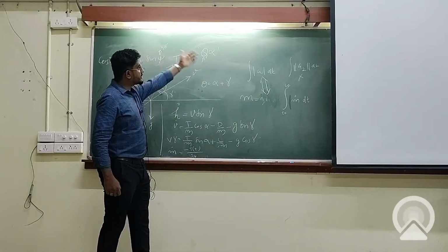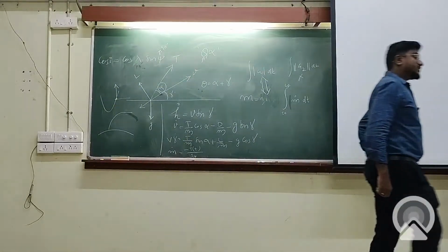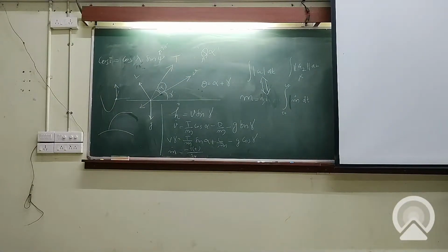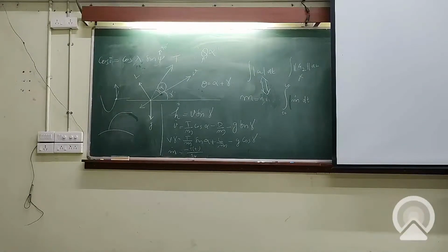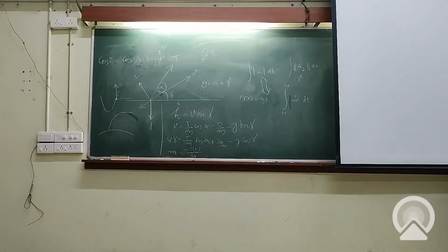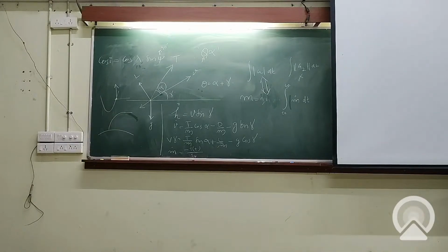So that is how we address this constraint called the structural load constraint. And there are a lot of issues there, like what information do we have about the relative velocity vector? It is not just the thrust, there is a major perturbation called wind. We don't have a handle on the wind. So usually we do this thing called DOLA, day of launch. Basically, we measure the wind maybe an hour or two before the launch. Then with that we optimize the trajectory so that the dispersion due to the wind will be less.